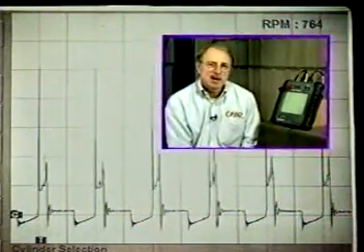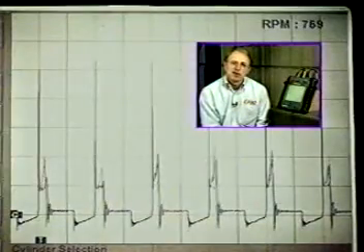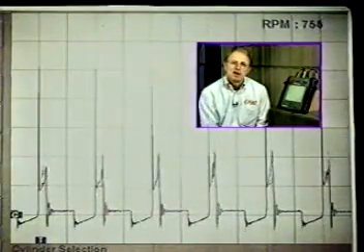You'll notice our firing voltages actually exceeded the screen. In other words, they went to 16, 18 kV. That basically tells us that compression is good. Now, mechanical integrity of the engine has been pretty much verified. So what I'd like to do right now is go to a single cylinder one at a time, and let's focus on the spark lines.